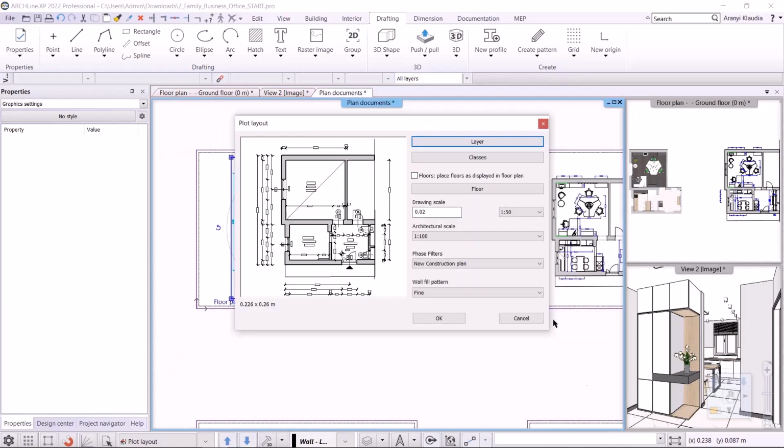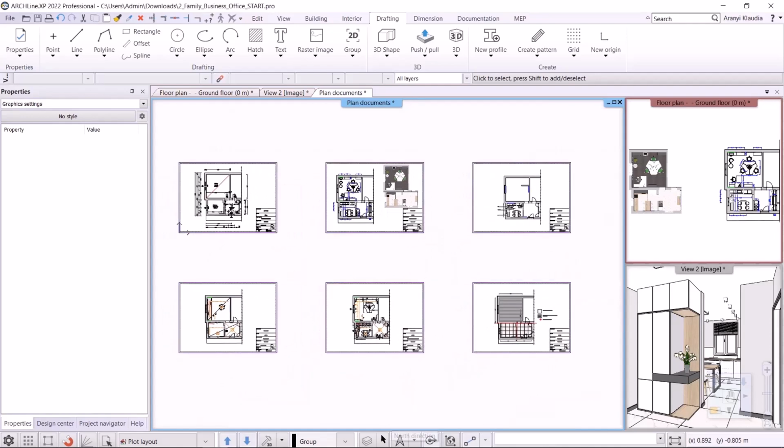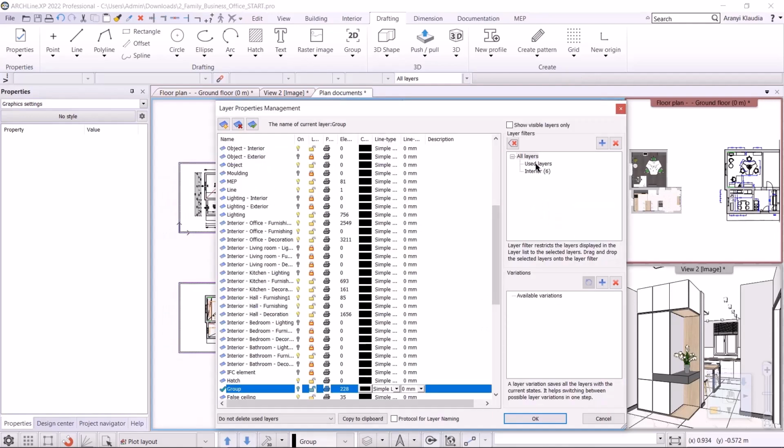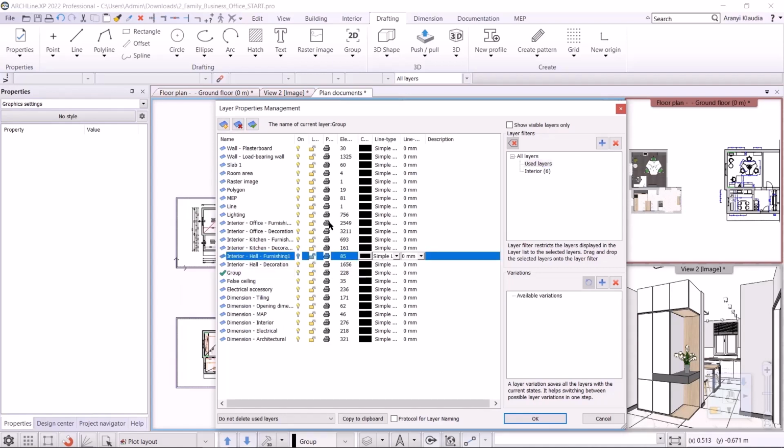It is important to note that there is also a layer set for the print sheet. If we go to the Layer Manager and look for used layers, we will find them here. Also important, as I mentioned before, is that this column is responsible for printability. Always make sure that this is turned on for all used layers, because if it's not, they won't show up in the print. As I mentioned, turning off printability can actually be interesting when working with edit lines.